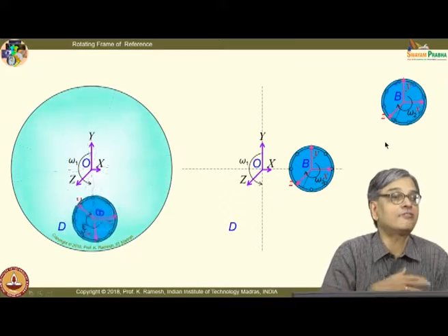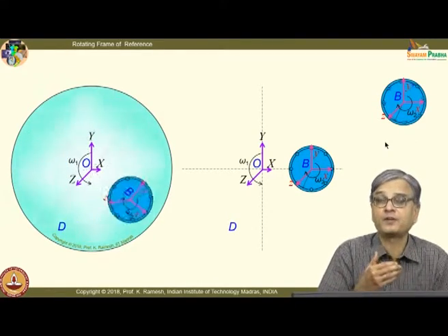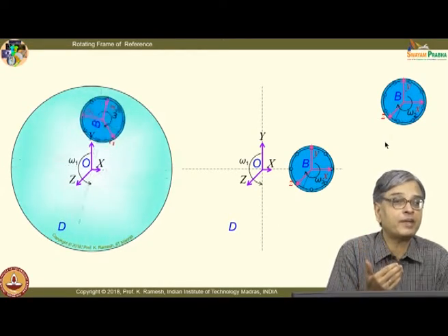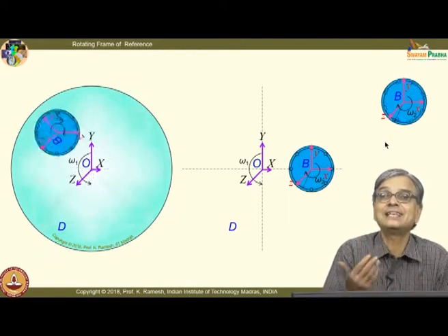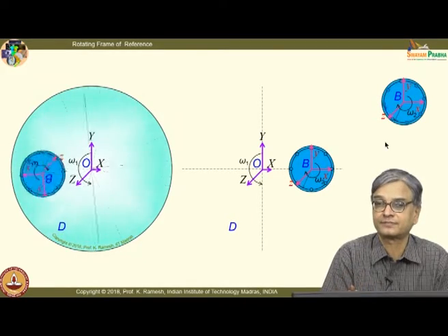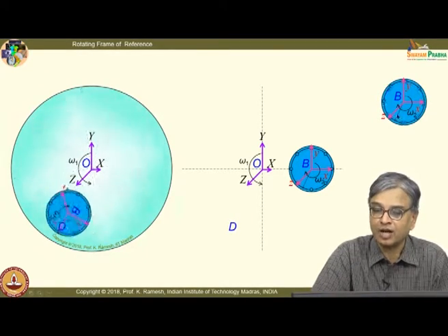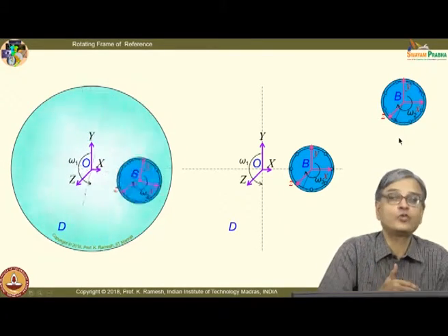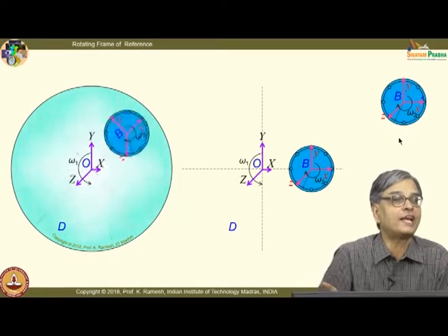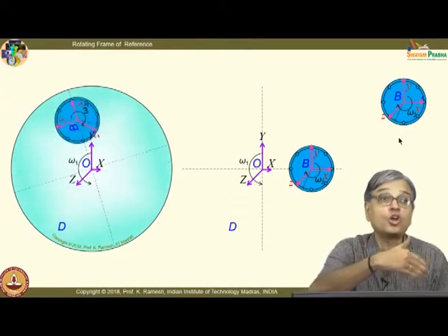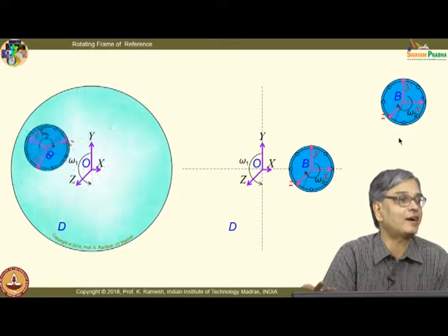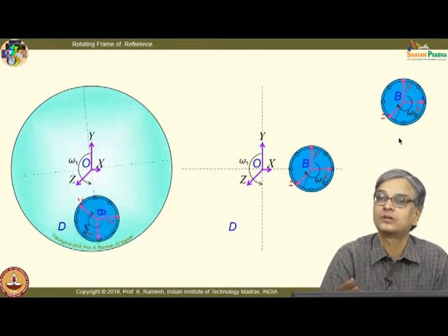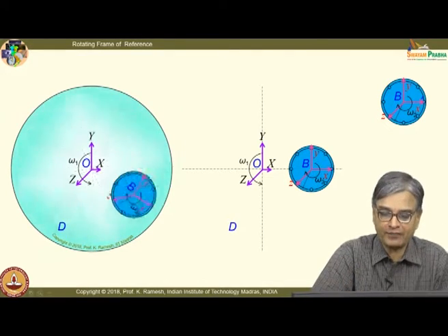So, this is the way that you will have to understand the relative, not the relative velocity, the velocity from a rotating frame of reference, you can easily calculate based on circular motion. In this case, the object is rotating in a circle. While we developed the theory, we took a rigid body with a slot where the point A is moving within a slot. That is more complicated motion. Here the motion is far simpler, you do not need any new equations, the equations you already know, fine. Let us also look at it from a different perspective.